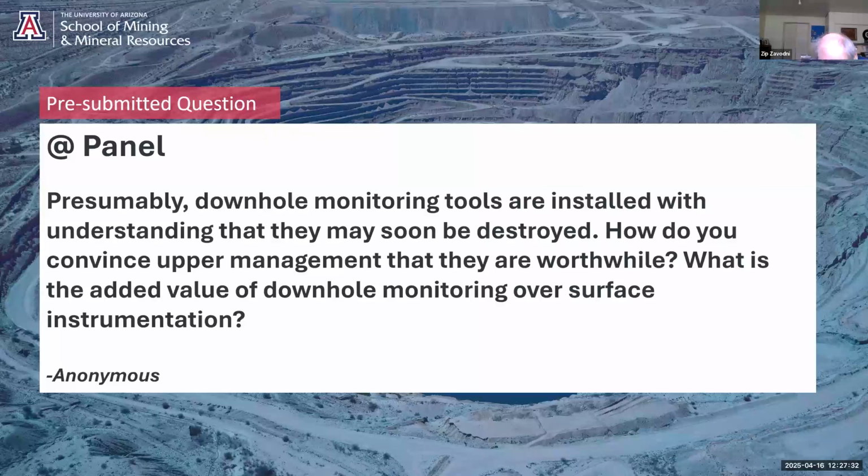And our systems now are sophisticated enough to give us this advanced warning of very small dilations, but they are subsurface. So a good shape array system and inclinometer system is extremely worthwhile, and I think can easily be justified to your senior management as a worthwhile installment and investment.